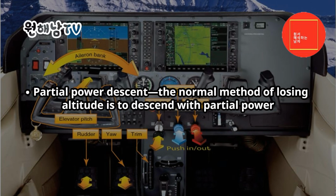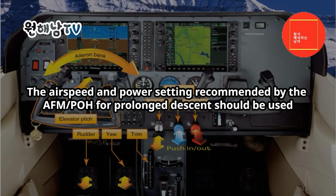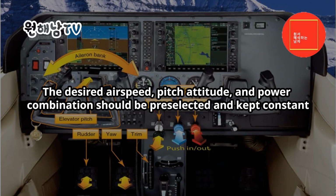The normal method of losing altitude is to descend with partial power. This is often termed cruise or en route descent. The airspeed and power setting recommended by the AFM/POH for prolonged descent should be used. The target descent rate should be 500 fpm. The desired airspeed, pitch attitude, and power combination should be preselected and kept constant.